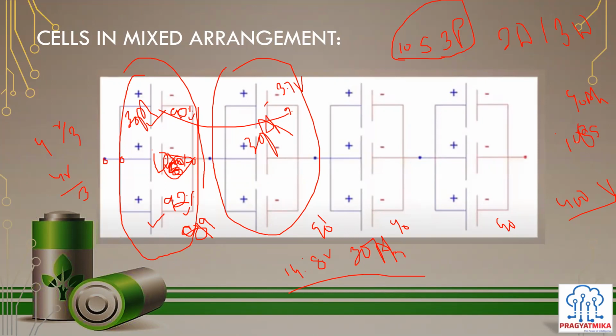Now there is no such BMS available in a single assembly which can measure 108 series cells in one BMS. So there also the master slave architecture would be followed at a module level. So master slave is not the restriction factor for this. It is the number of cells, how they are connected, and how many cells we have to monitor in the battery pack. That is what determines the selection of your BMS.